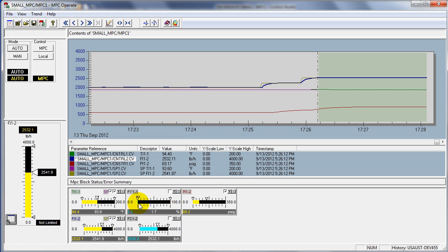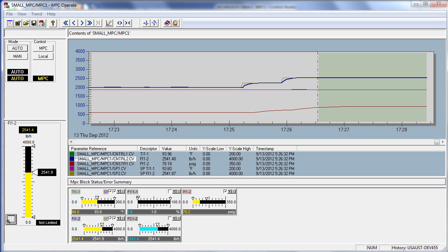The cooling valve is fully open, the heating valve is closed. And so we're now operating at the capacity of the unit. We really can't stand to have any more throughput. There's no cooling capacity, and in this kind of application, the temperature could continue going up if we exceed the capacity of the cooling unit.